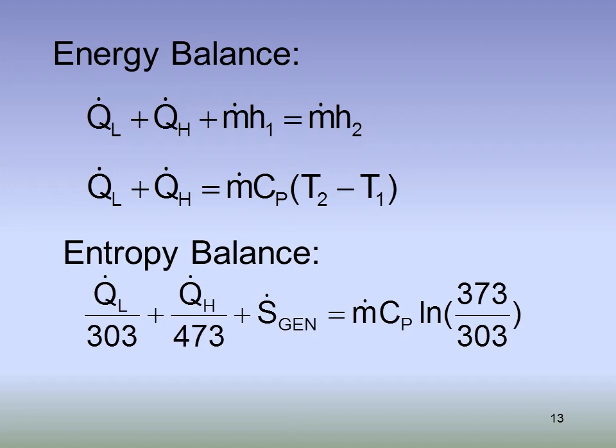So you recall there's two equations for the change of entropy of an ideal gas, and one of them uses Cp: Cp ln of T2 over T1 minus R over molecular weight ln of P2 over P1. The pressure is not changing, so that part will drop out, and you only have the temperature change to be concerned with.